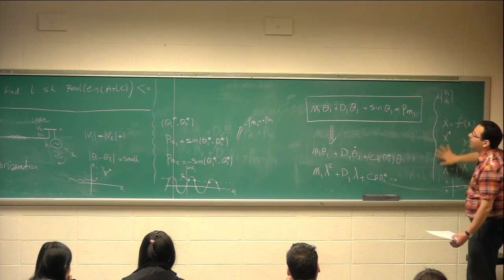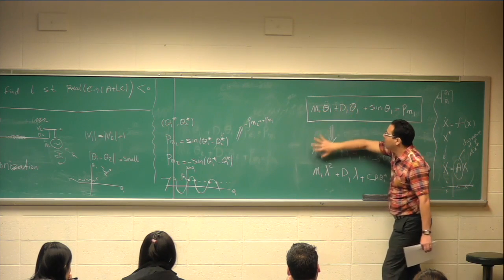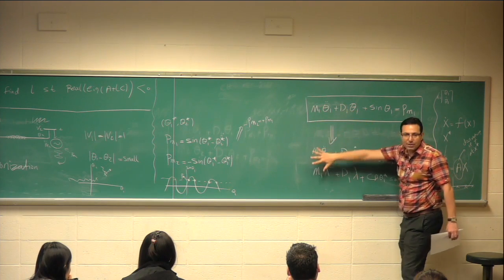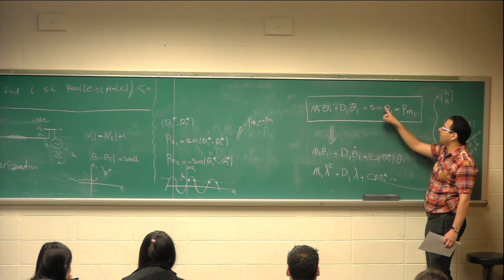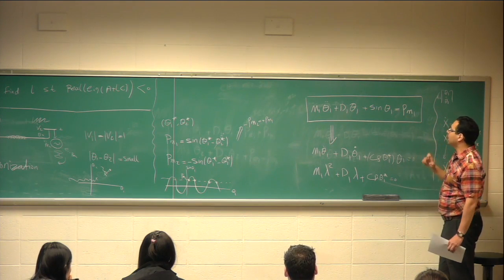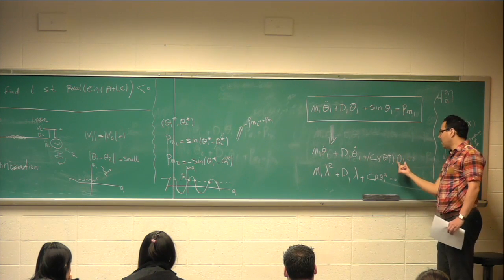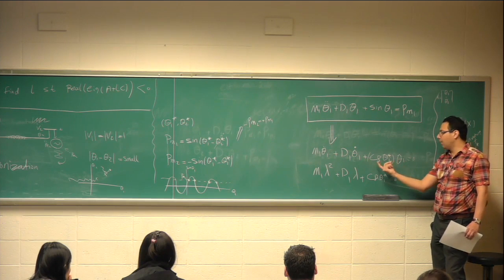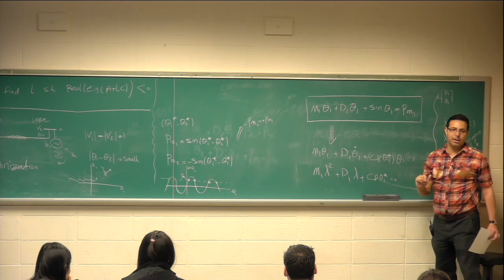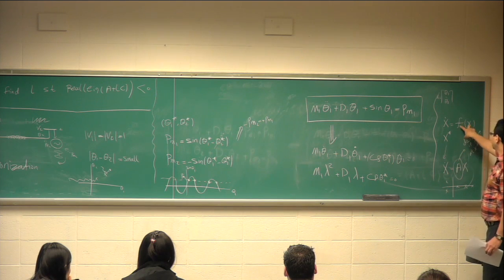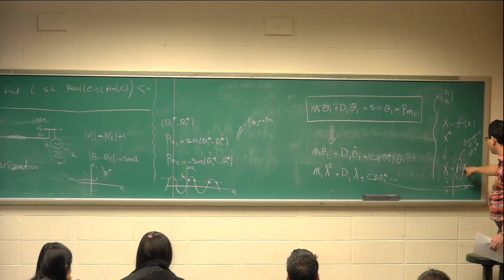But if you do it that way, eventually the main idea becomes the following. All linear terms would be carried over. All nonlinear terms, like sine of theta 1, are going to be replaced by a linear term. A linear term is a line. So there is an argument, which is theta 1, and a coefficient. What is the coefficient? It's the derivative at the equilibrium. So this function, f of x, is replaced by a plane, Ax. So x is the argument, A is the derivative.